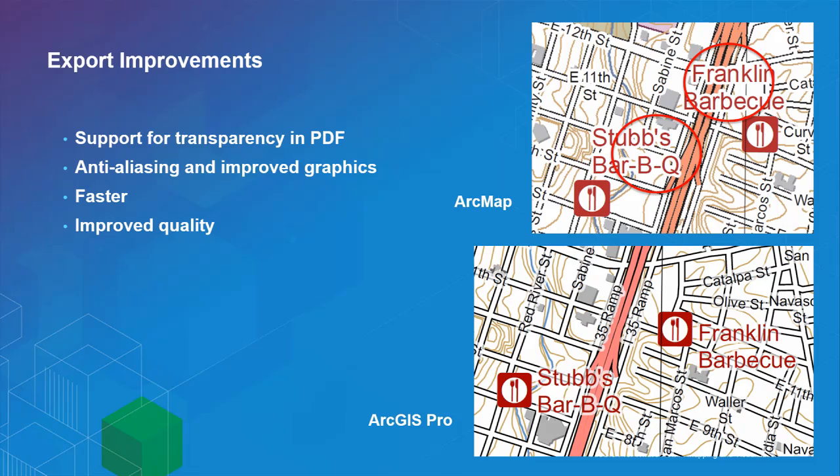You'll notice it's knocking out all the roads. On the bottom, this is one in ArcGIS Pro. We're actually just applying a transparency to those, so you can subtly see the roads through the text halo. It's just kind of a nice effect you can get from applying transparency to a color and to a very specific layer within your symbol.